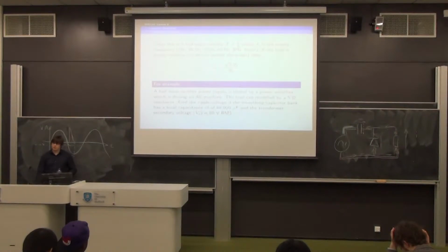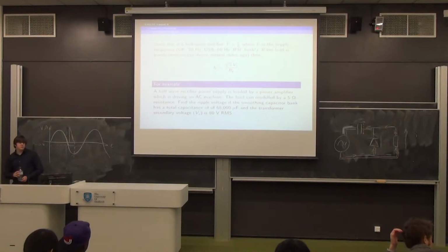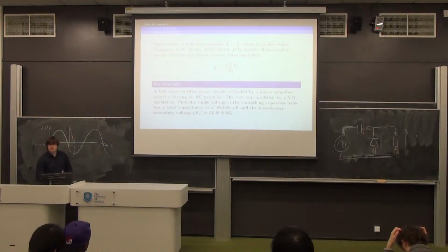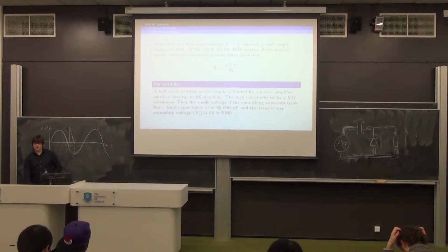But we'll do an example shortly. So in this case we can say for the purely resistive load, the load current is √2 times Vs upon RL. The √2 turns up because we're saying it's sine waves everywhere, and the relationship between the peak of the sine wave and its RMS value is √2. Vs upon RL is Ohm's law. I is V upon R.